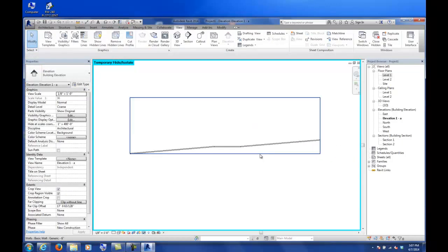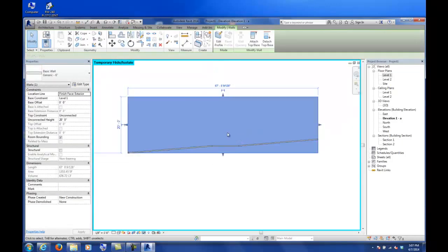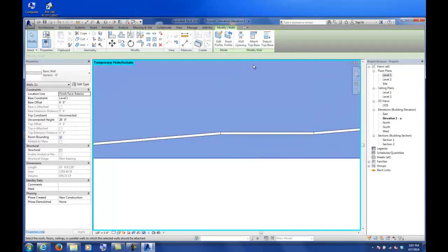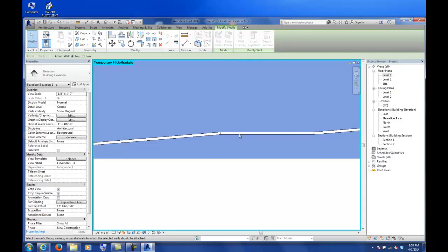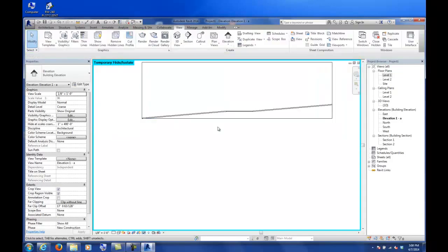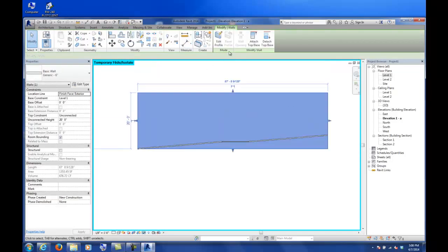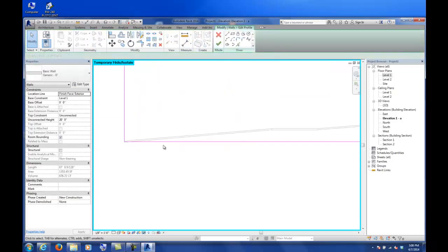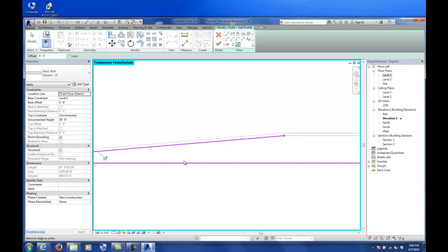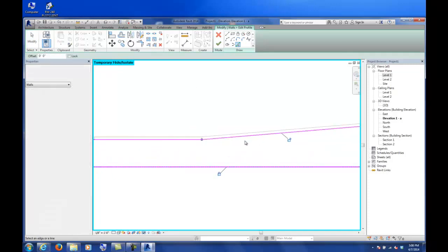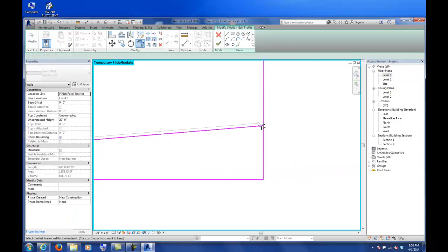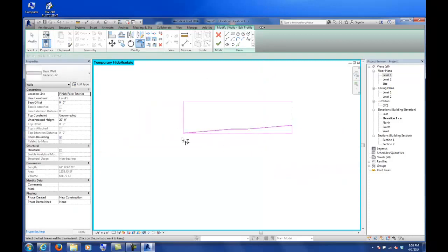Sorry, no, actually, we were kind of wrapping up. So what you would do here, if you remember in one of the very first classes when we talked about editing wall profiles, is where Edit Wall Profile comes in handy, because this is a ramp. We can't actually attach it to that surface unless it was a floor or a roof or something like that. Because it's a ramp and it doesn't recognize that tool as of right now, we can click Edit Profile, and then you could pick lines, and I would go around and pick the top of that ramp, and then you just need to make sure that you trim, close those together, and then delete that other line.